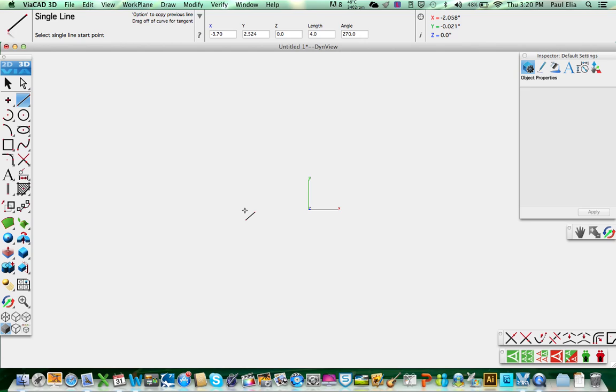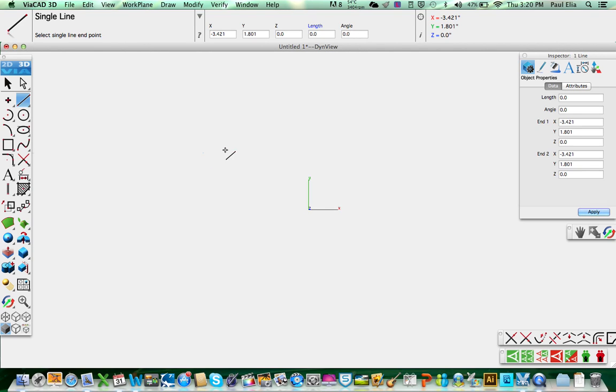In this tutorial, we're going to look at making a surface using curves. We're going to go back to a very simple drawing we made earlier, which is the 4 by 4 inch drawing. So let's just do 4 inches, and 4 inches, enter. Click 4 inches again, 4 across, 4. And we can just finish it off like this, just 4 inches.